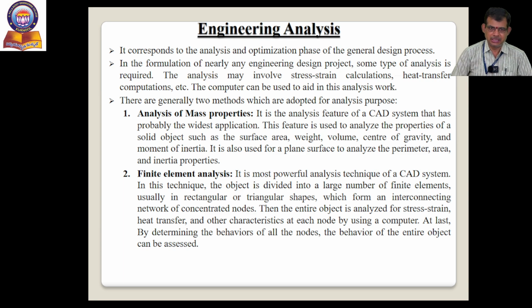So in this technique, the object is divided into a large number of finite elements, usually rectangular or triangular shapes, because they are mathematically definable forms and it is easy to do the analysis also, which form an interconnecting network of concentrated nodes. Then the entire object is analyzed for stress, strain, heat transfer, and other characteristics at each node by using a computer. So in order to fulfill your requirement, you will carry out at the nodes, at the joining of these interconnected elements.